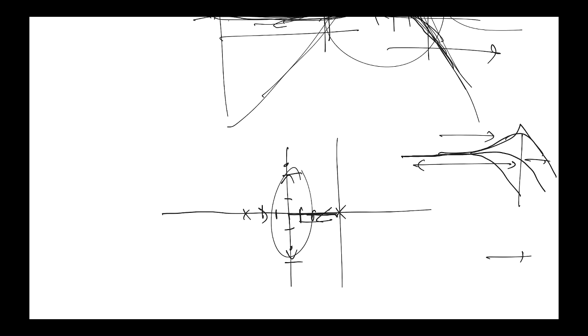And we've seen examples. If you go and look at problem set 4, there are 2 cases considered. In one case, pushing the crossover frequency to the right led to an improvement of the phase margin and reduced the peaking. In the other case, pushing it to the right reduced the phase margin and increased the peaking. So there's no generic rule that you can come up with. You just have to look at the situation you have and understand what the phase margin means and how that relates to how much peaking you get in the sensitivity functions.